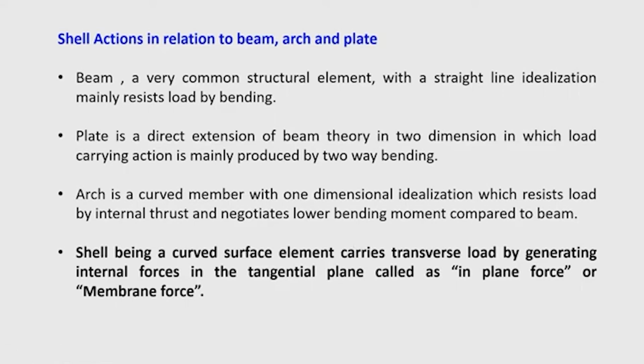Now, a beam is actually a very common structural element, generally a horizontal member, with a straight line idealization that we can do in structural analysis. Whenever a beam is loaded in the transverse direction, it receives the load mainly by bending. The normal thrust and other actions are minimal in the case of a beam.